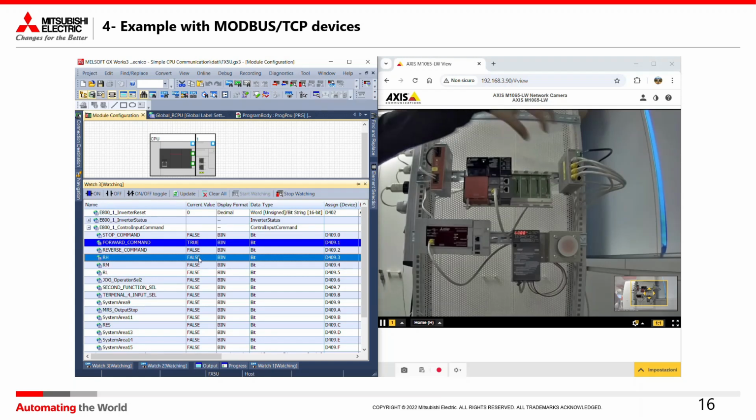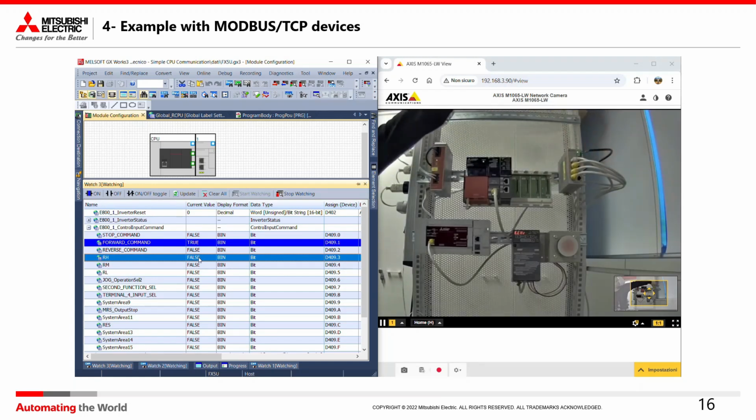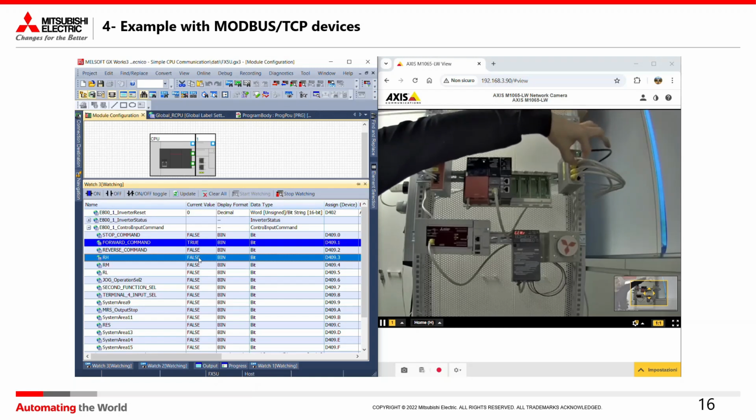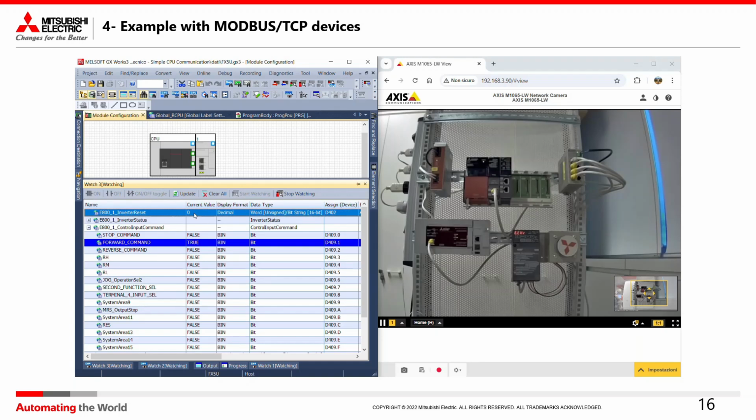As a final test, we simulate the disconnection of the inverter Ethernet cable, where the error is reported with the consequent stop of the motor. The action that the inverter must take when it loses the communication can be managed by parameter. After reconnecting the Ethernet cable, by sending the reset command, the inverter restarts with its acceleration ramp up to the previously set frequency of 60 Hz.